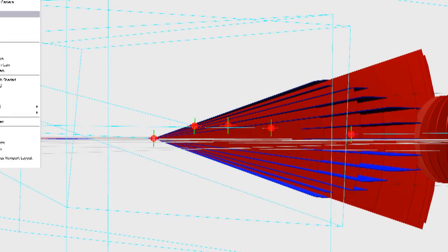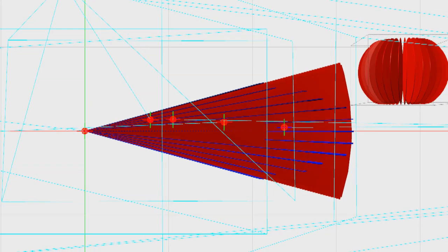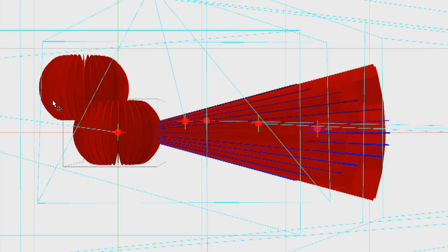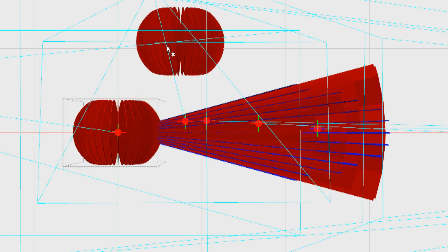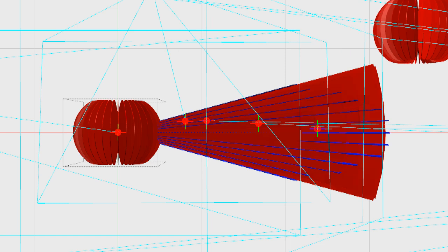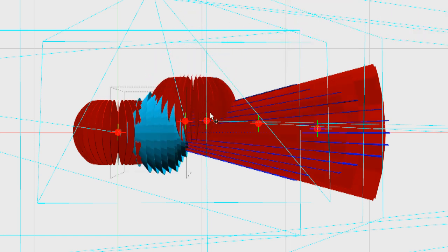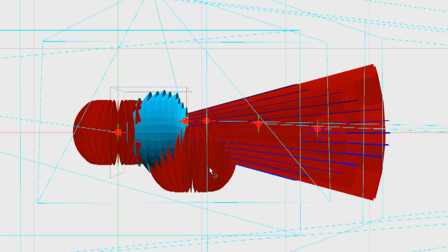So let's go back to the front view, and let's turn on this, your plane here. To compare, we've got the rubber ducky, which gets you to about here. However, the benefit is we can fly right behind ourselves if we want and we'll still be in range, assuming we're not too far away, omnidirectional. And then we have our circular, which we can get a little bit further. And remember, it's less sensitive to your orientation of the plane, so it's a little bit more of a consistent range.